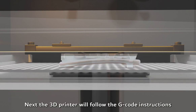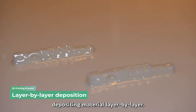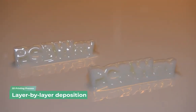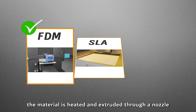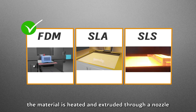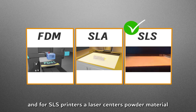Next, the 3D printer will follow the G-code instructions, depositing material layer by layer. For FDM printers, the material is heated and extruded through a nozzle. For SLA printers, a light source cures the liquid resin, and for SLS printers, a laser sinters powder material.